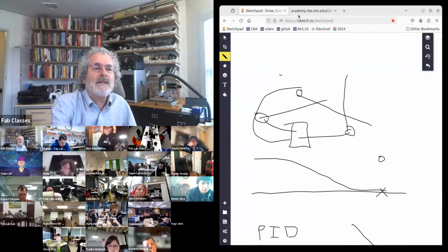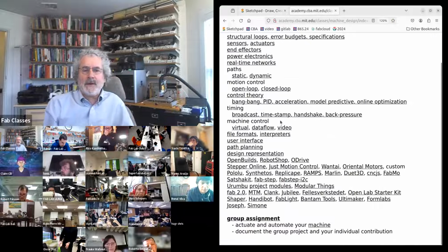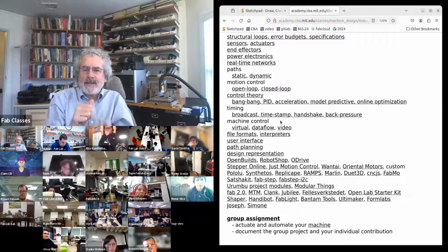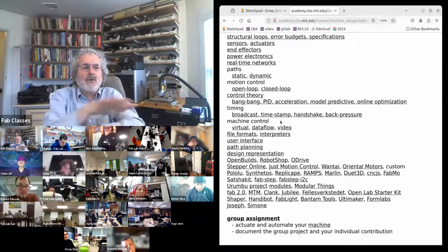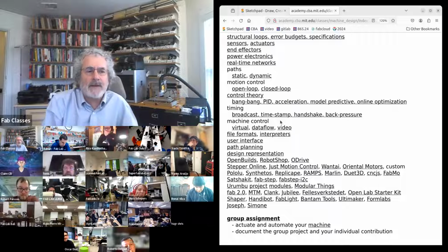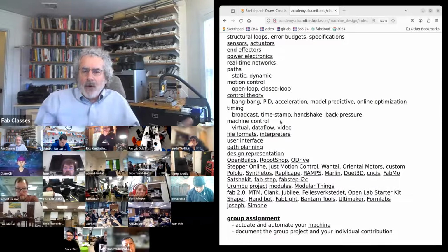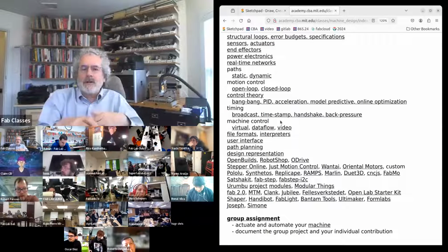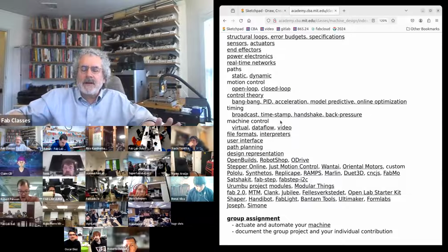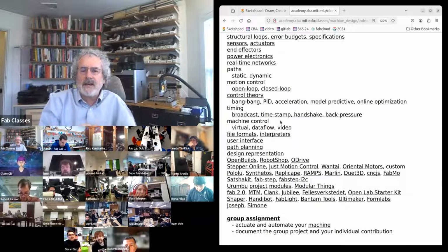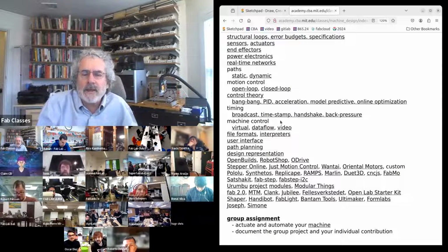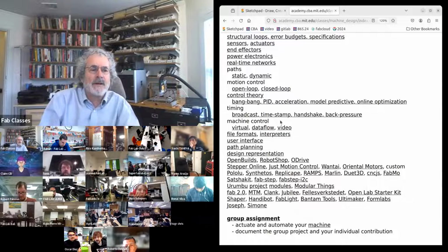And so we need to coordinate the machine so that each axis moves in a coordinated way. If they're all plugged into a central controller with one processor, you can do it. But as the machine gets bigger, there are multiple processors. So then you need to use the networking things we'll be talking about to coordinate.